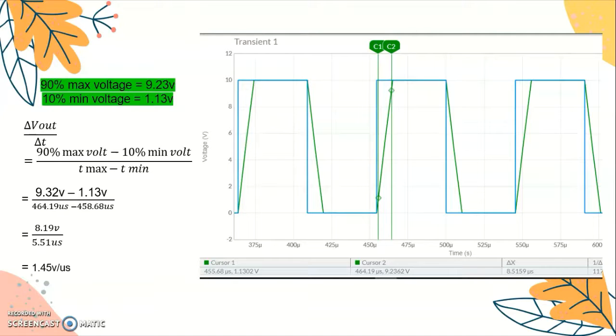So the time taken by the operational amplifier to reach that level, in volt per microsecond, depends upon the slew rate of the operational amplifier. For the general purpose 741 series operational amplifier, the value of slew rate is 0.5 volt per microsecond.